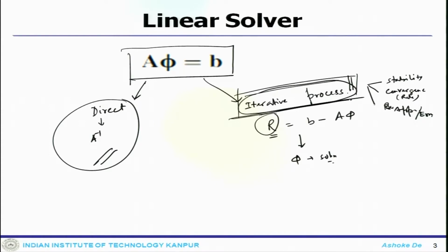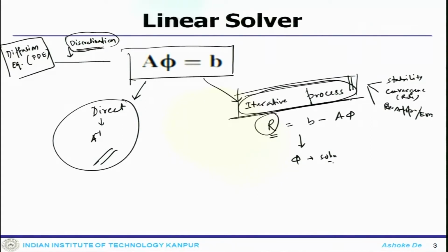So, if you look at the picture, you have a system, basically you had the diffusion equation. Since we have discussed the diffusion equation, that is nothing but the PDE. You apply discretization, and regarding the discretization, whatever issues that can be associated like structured grid, unstructured grid, orthogonality, non-orthogonality, gradient computation, boundary condition, everything is included in this block of discretization, and once you apply that, that leads to the linear system.